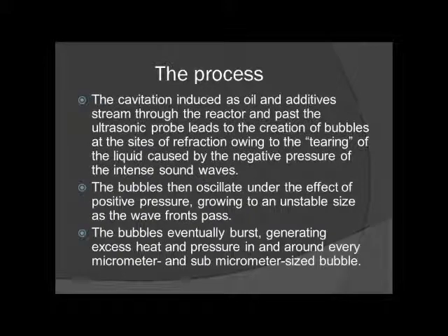Then the cavitation induced as oil and additive stream through the reactor and past the ultrasonic probe leads to the creation of bubbles at the site of the refraction, owing to the tearing of the liquid caused by the negative pressure of the intense sound waves. The bubbles then oscillate under the effect of positive pressure, growing to an unstable size as the wave fronts pass.